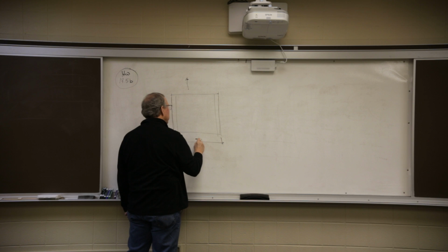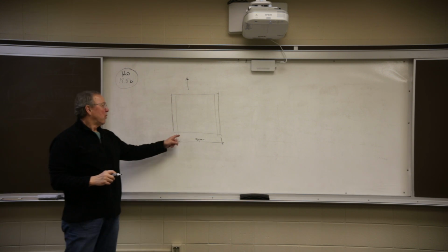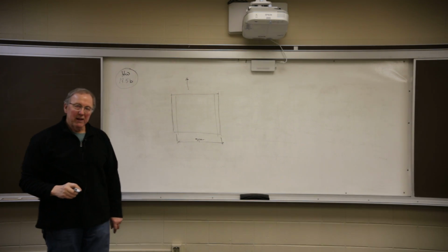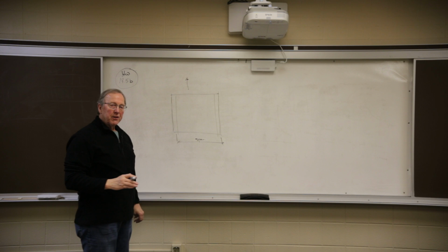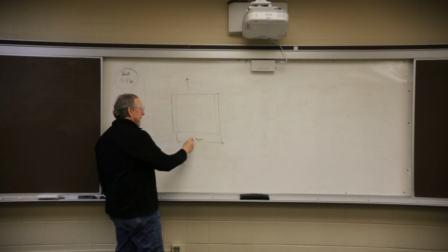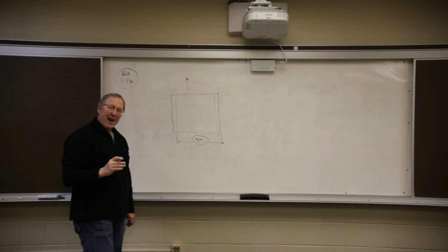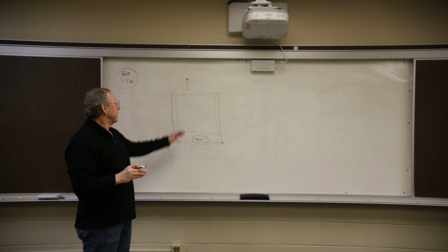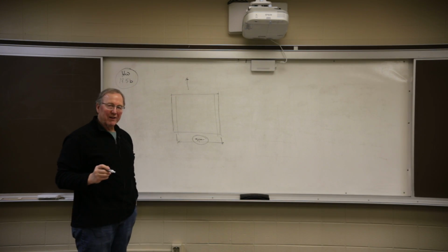And the span width typically on a single or a simple one-way slab is relatively short compared to the length. Typically in the engineering side of it, we limit the span width to 1/2 or greater than the span length. That's why they call it a one-way slab.